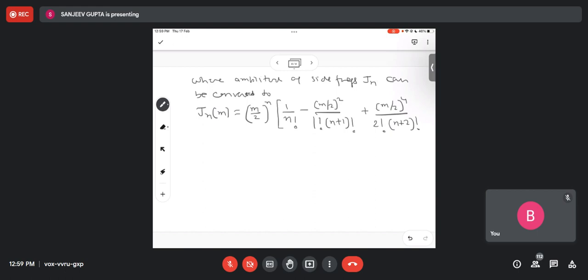So there is a Bessel function, as I told you, given by this first equation in the slide. We compare it with our FM equation and see which parameters match. Alpha is equal to omega C and beta is equal to omega M. On the same line, the solution as an expanded series, I solved it, so we got this expression. Last time I just simply put the expression. So this is how we have this amplitude part, which is the J n M part.